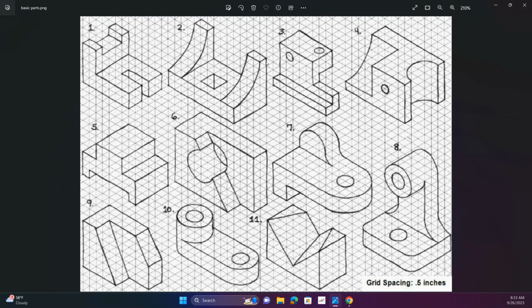So 3 inches tall. Now, one thing you'll notice here is there's a circle. This circle I've given you is a quarter of the circle, because the circle is going to go all the way around. If we go down here, I can figure out this circle is 1 inch, 1.5 inch, 2 inches. So this quarter of a circle is 2 inches, which would mean that my circle is 4 inches in diameter. Okay, so that's going to be very important when we're putting this together.